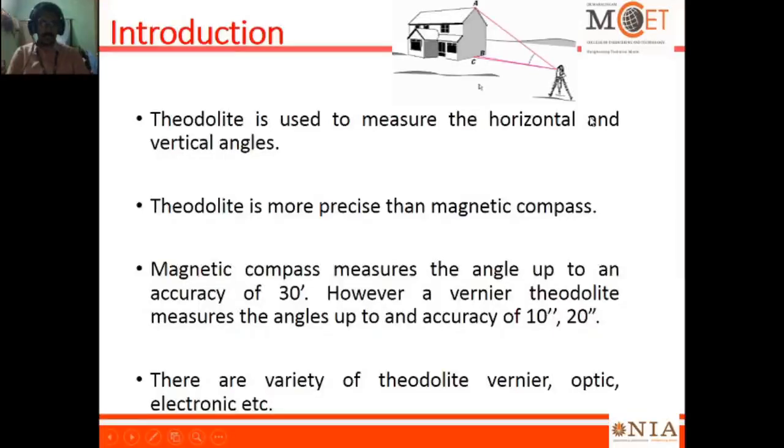That is the thing. With the theodolite we can measure both the horizontal and the vertical angle, such that from our straight line of sight we are able to measure the vertical angle also, and if it is perpendicular to it, you obtain this angle. Based on mathematical logic and trigonometrical principles, we can determine the horizontal distance and the vertical distance also. Similarly, if I measure the angle between this end and that end, that is a horizontal angle, I can obtain the distance of the object without touching it.